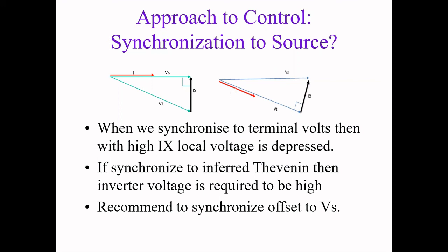Yeah, thank you. I think we've got to be careful about the word weak grids. Here I've been using it as a Thevenin impedance type term, but when we're dealing with operations and oscillations, that's usually a small signal term, and inverters can help strengthen grids in the small signal. So the effect of strengthening by control of inverters is quite feasible and possible and should be used.